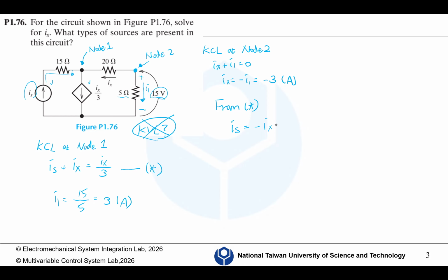So this is positive, negative, 5I1, and this is positive, negative, 6 times I1 minus I3 because it is shared by I1 and I3, and this is negative, positive 2Vx, but Vx is 10 times I3, so 2Vx equals 20 I3. And this is positive, negative 8 I2.